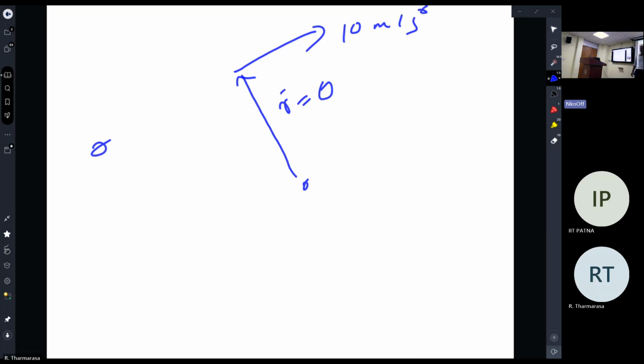That is a limitation. When it comes to track initialization, I don't usually use the range rate because that is not fully observed, but still you can. If you are somewhere here, then the measured range rate could be, for example, 6.2 meters per second. That is the range rate at this time. So it definitely has information.